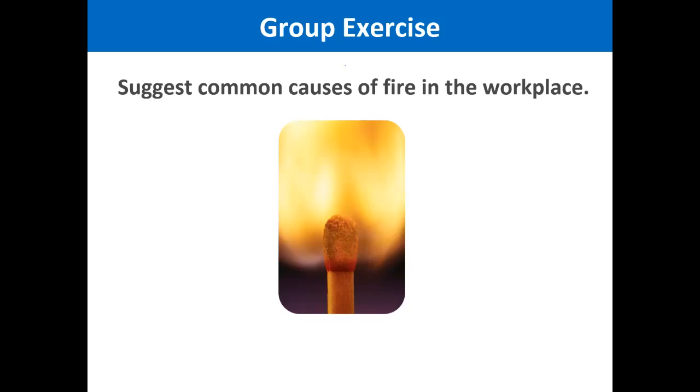The welding works near the combustible material, sir. Exactly. Carrying out hot works, carrying out welding, cutting, grinding near combustible material. That is a cause of fire. Okay. What other causes of fire can we have? Mohsin? Sir, flammable substances at the workplace. Storing excessive flammable substances at the workplace, yes.